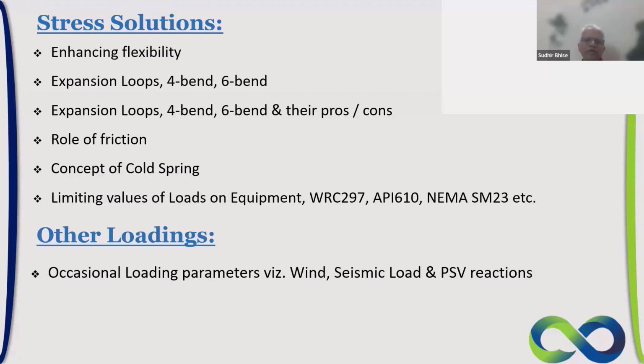The other loadings that we are going to see are the PSV reactions, that is direct force, the wind reaction, that is the pressure force, and the seismic load, that is the acceleration loading. And we are going to study how they are going to affect the already displaced system, and what are the limits of the stresses applicable, and why the system should be made safe in those cases also, and how it